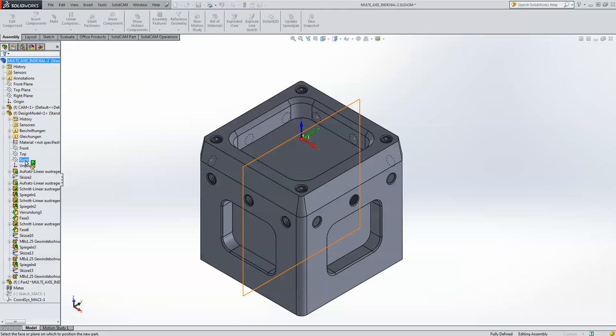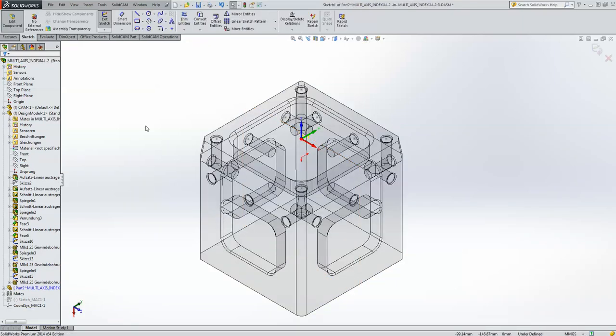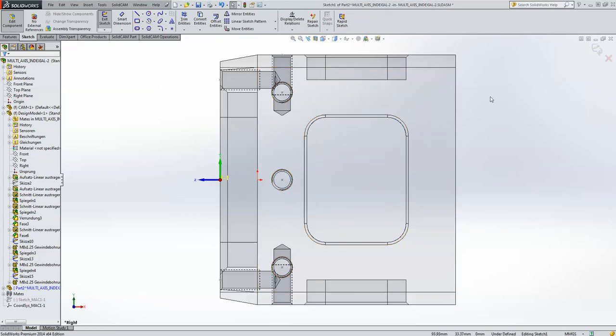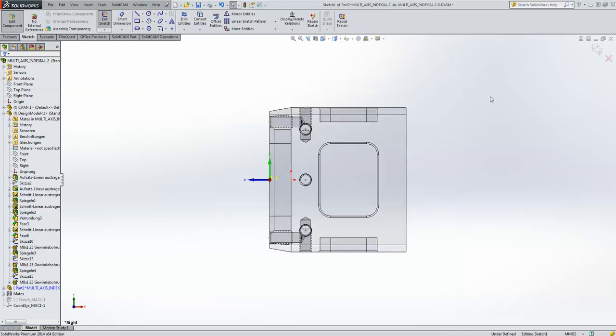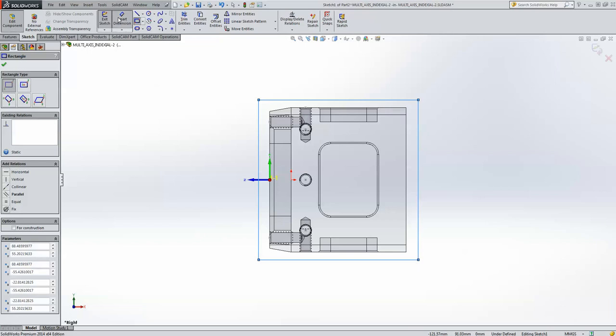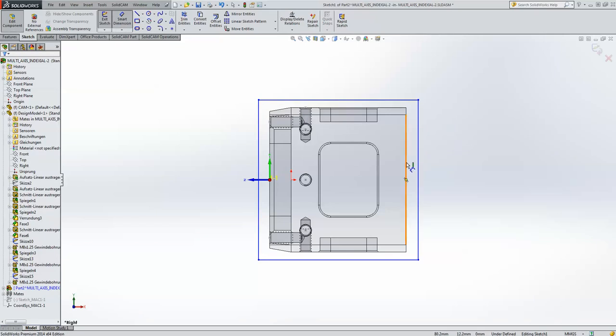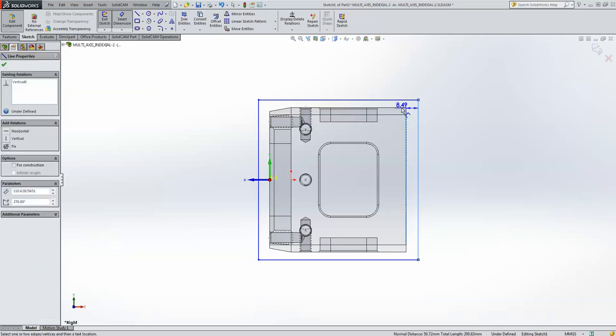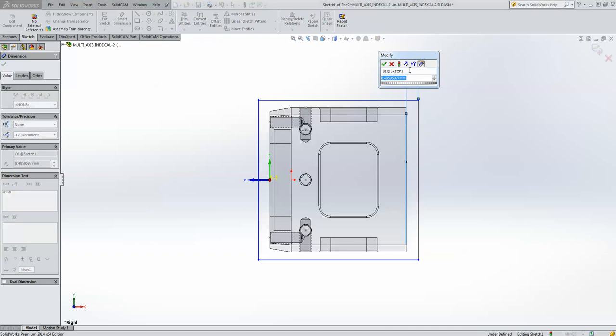That's where I want to create my sketch, and let's put it in a way that I can see exactly where I'm going to work. Now I'm going to do exactly what I did before, and create my stock the exact same way, no difference, put in my measurements, but this time I'm building a separate part outside of the actual part itself within the assembly, but it's going to be associative to the part itself because I'm taking the measurements